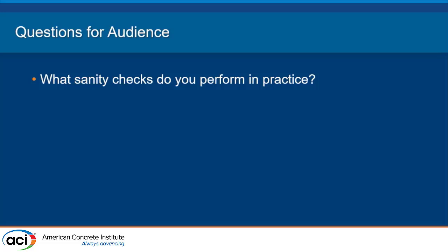I have a question for you. When you dealt with that sinking, the caisson, for example, how do you handle the settlement between the caisson and the surrounding soil? How did you account for the slippage that takes place? Because that's one area where people do tend to overcomplicate the model, sometimes don't get it right. So I'm just curious to know, how did you guys handle it typically?